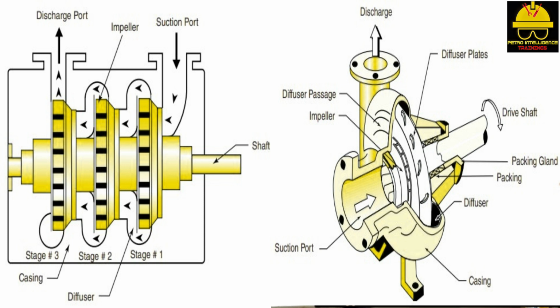As back pressure builds in the impeller, gas velocity is accelerated through the diffuser assembly and into a circular volute. As high-velocity gas moves through the diffuser and into the volute, kinetic energy is converted into pressure as gas speed slows in the ever-widening volute before exiting the discharge port. Because compressor performance is linked to the compressibility of the gas it is moving, centrifugal compressors are more sensitive to density and fluid characteristics than are reciprocating compressors.